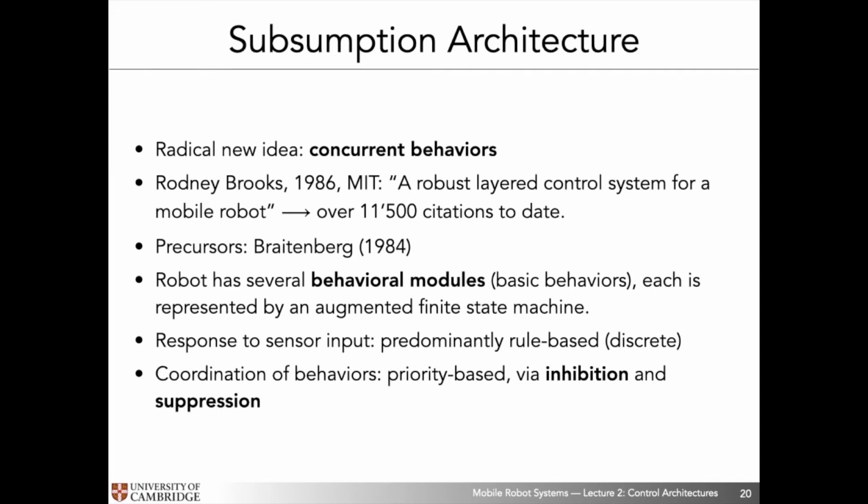a hierarchy of behaviors where you might have the most important ones in the bottom and the least important ones in the top, and you can in that way construct what hierarchy or what kind of inhibition mechanisms you would like to see happening in case of a cascade of rules being triggered. Right? So that is the key of this control architecture. So let's have a look at what this control architecture actually looks like.